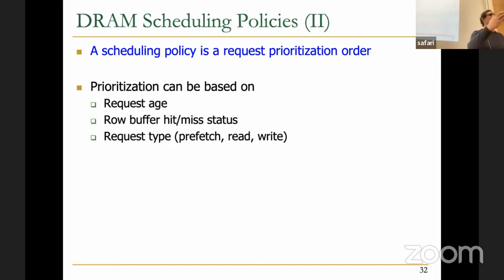You actually schedule the prefetches that go to a row buffer that's open and get them out quickly, and maybe delay some reads that you know are actually demand reads, as opposed to letting those prefetches, let's say, not be serviced for a while, service this read that will close the row, which will take time, and then service the prefetch that will close the row and open it again. So as opposed to causing more bank conflicts, you may actually be better off not causing the bank conflicts, but prioritizing a prefetch request, for example. So it's good to think about these decisions.